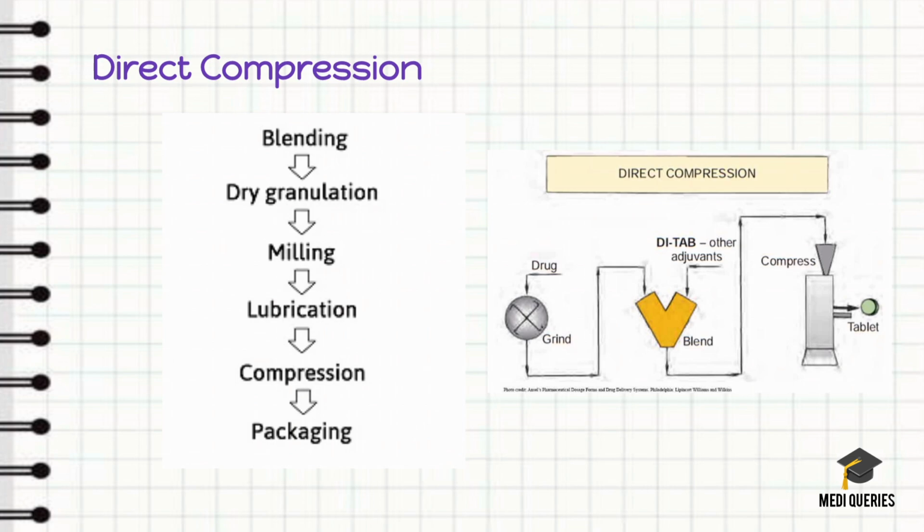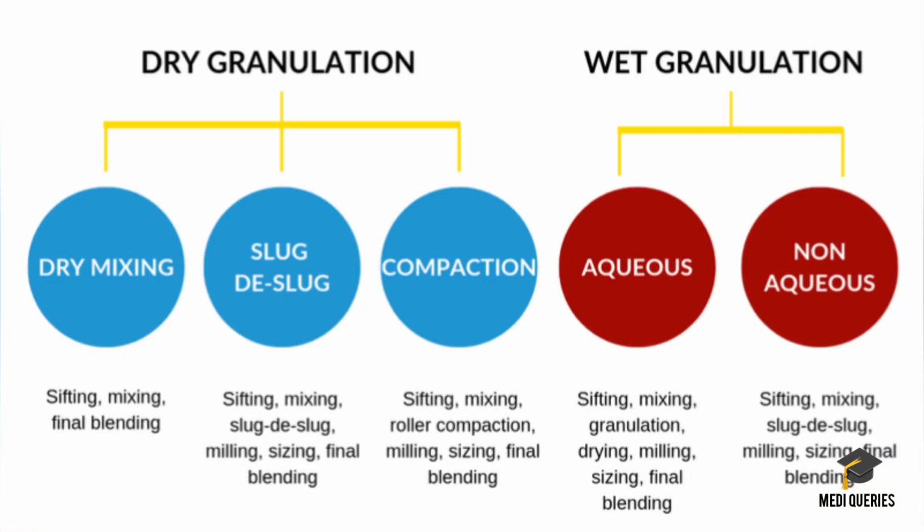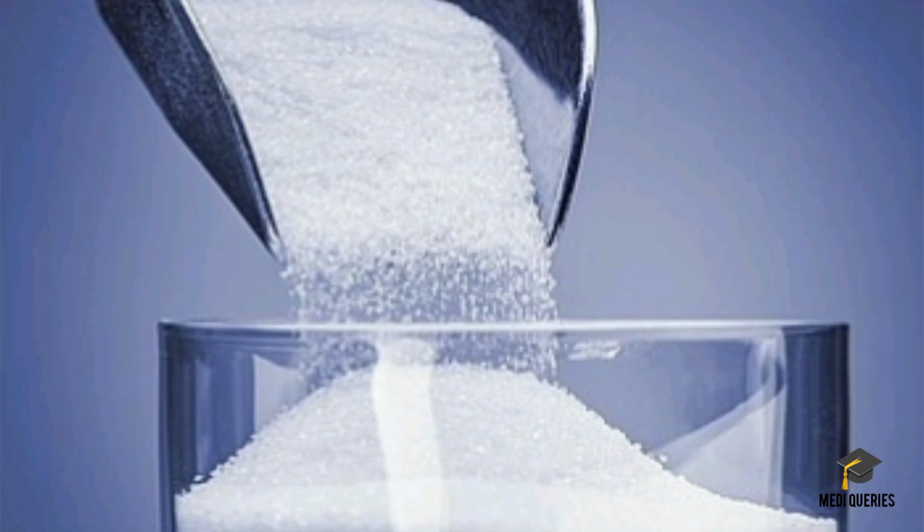Okay, so here is a small summary for all these methods. Wet granulation offers the best control, but is complex and costly. Dry granulation is moisture free and efficient, but limited by powder properties here. Direct compression is the most economical and the fastest, but requires specialized equipment.